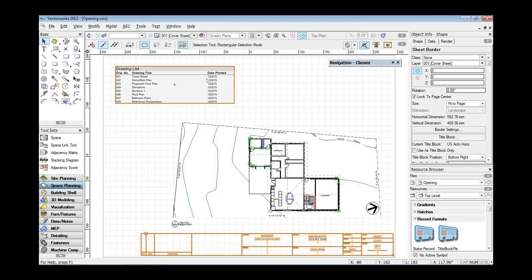A report in Vectorworks is an ability to attach data to things, link text to record they call it. So we've got this concept in Vectorworks called record formats. That's these things here. And your record formats allow you to attach non-graphic information to objects. So the technology of record formats is what allows us to attach things to windows, doors, walls, title blocks, and so on.